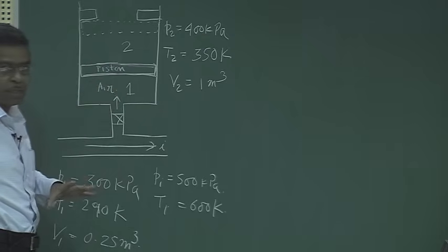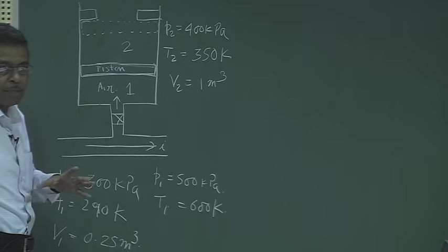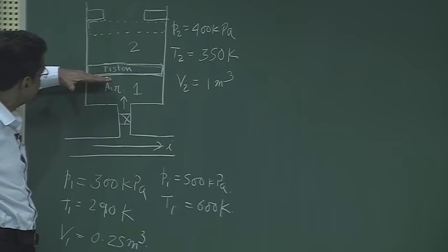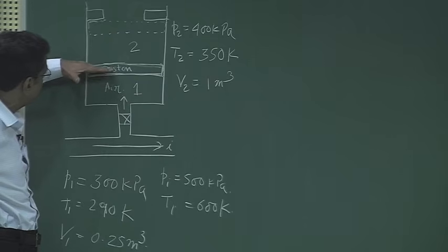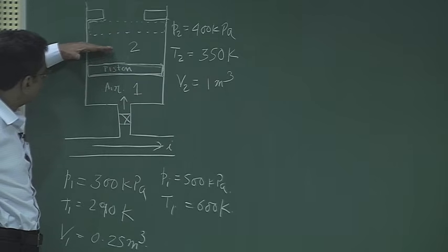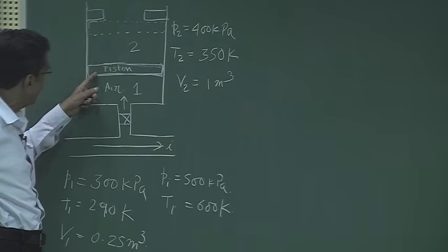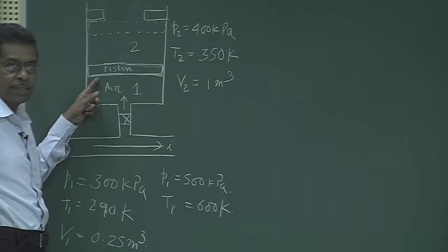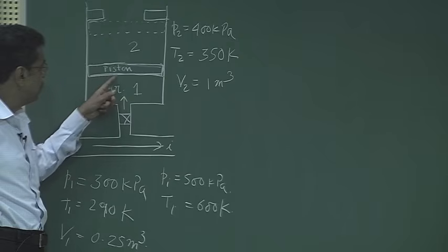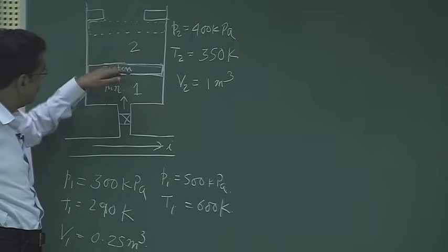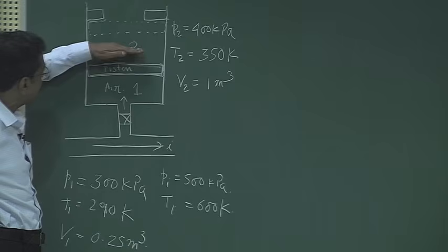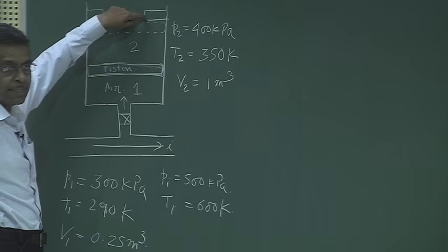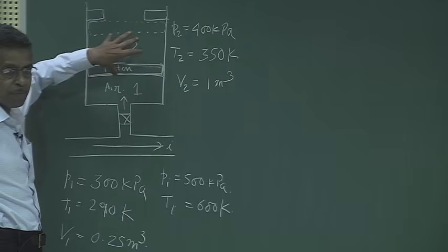You have already come to know what is meant by a quasi-static process. That means it is a very slow process, which passes through a number of equilibrium states, expanding in such a way that the weight of the piston is always balanced by the pressure force within the air. So at every instant the pressure is the same until it hits the stop. That is the pivotal concept of this problem.